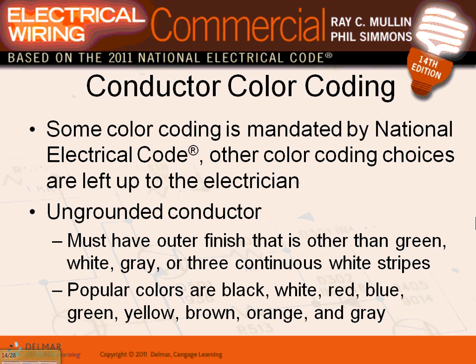You have to. If you have only one voltage system, like the building that we use, Chris, only one voltage system for all practical reasons, as long as I use a green as an equivalent ground conductor and the white or the gray as a neutral, for all practical reasons, I can use black for phase A, phase B, and phase C, and that's okay with the code. Obviously, we don't do that because we want to identify by phase. So what they do is they color code like this: red, white, blue, with green as your neutral, and the other colors as your phase, plus the green as your equivalent ground conductor.